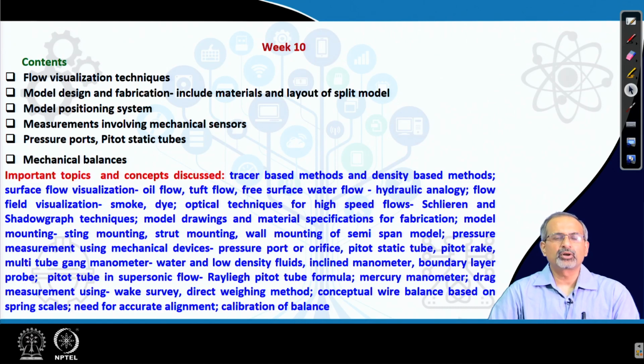How to do the model mounting. There could be different ways of doing it using sting mounting, strut mounting, or even wall mounting of semi-span models, or even full scale models where you do not have a symmetry plane, where the entire model can be put in the wall of the wind tunnel.